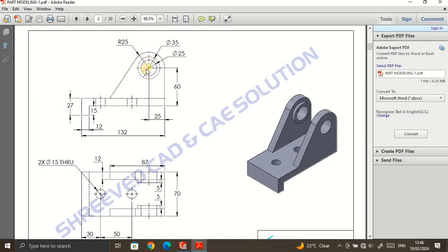Then we see the 25 mm outer circle radius and an internal hole of diameter 25 mm. The 35 mm is given for the extruded portion, that is a ring inside the plate. Both inside vertical plates have the inside ring with 35 and a 25 internal hole diameter. So for the external, initially we have to select a 50 diameter circle and the internal hole 25 mm diameter.